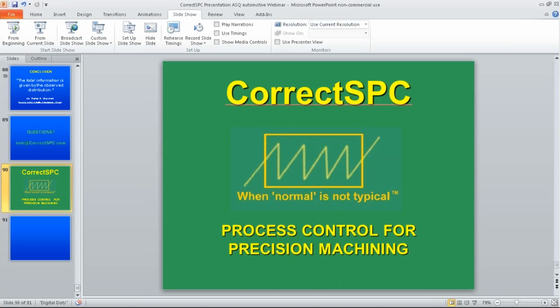If you look at the need of that type of adjustment, and I do in my plant, we have a grinding process because there's so much variation of the blanks going into it that we need to do that. And I'm still struggling with, okay, what can I do with this kind of a process, because I can't see anything that's going on because of this constant adjustment. But in the situations where we're able to see the tool wear rate and not adjust it that way, we know a lot more about the process. The engineers know more about the process. They can see when the machine's not working right. They can see when the tools aren't as good as they used to be. And you can't see it because it's all messed with adjustments. It creates more of a problem than an answer.